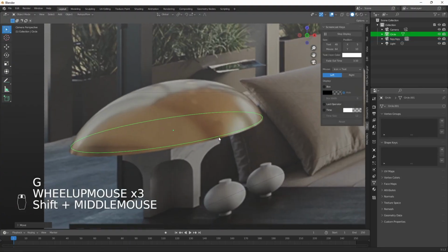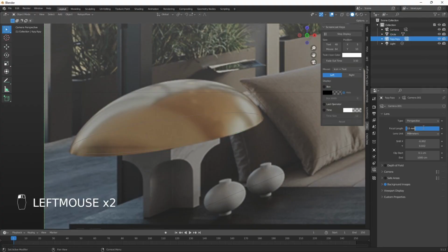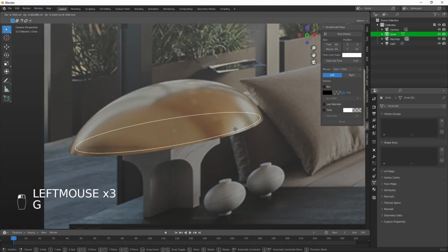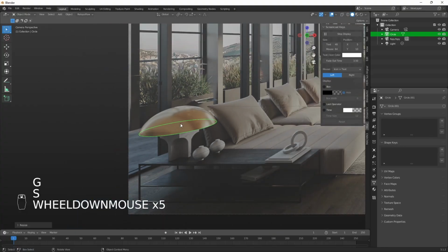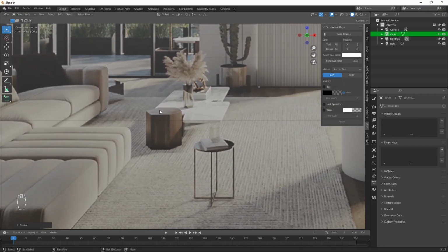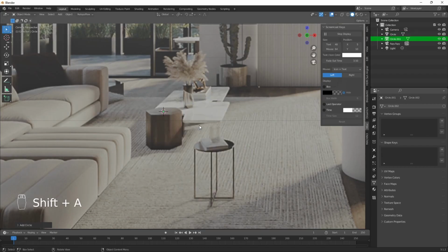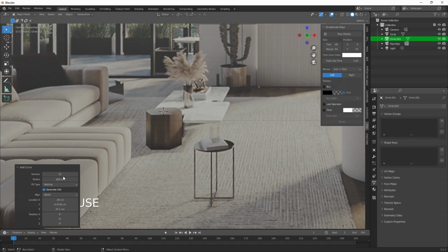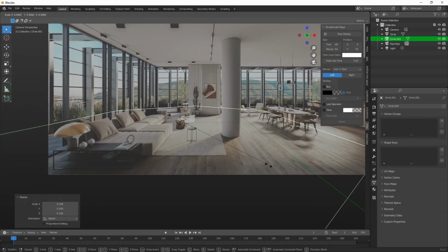Well, now it looks like it's stretched in the other direction, so I think I've overshot it. Let's try to decrease the value, and now it looks pretty nice. Okay, I'm gonna double check it by adding another shape here. This time I will use a hexagon. And to add a hexagon in Blender, you can select the circle and set the number of vertices to 6. So let's scale this down and...